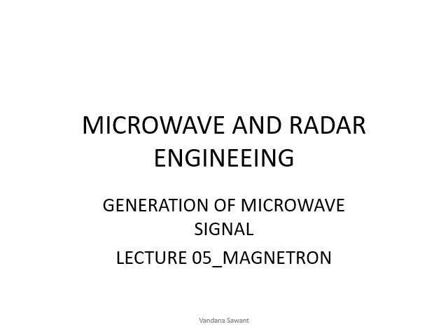The first difference is a magnetron is a high power generating device, so it can be used in a radar. It was invented during the Second World War. Then the second thing is that the electric field and the focusing magnetic field are perpendicular to each other. The electric field is in a transverse direction, the magnetic field is in an axial direction. So this is a cross field type tube, or we can call it an M type tube.